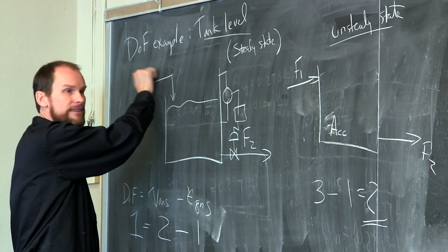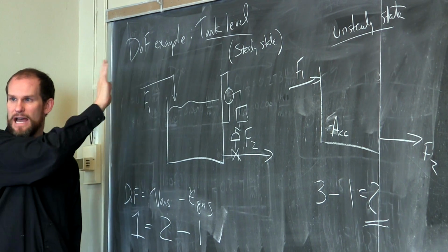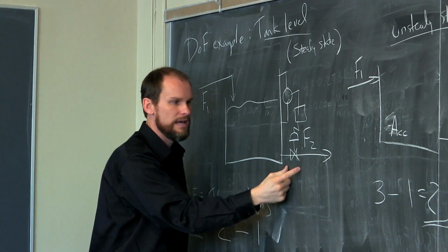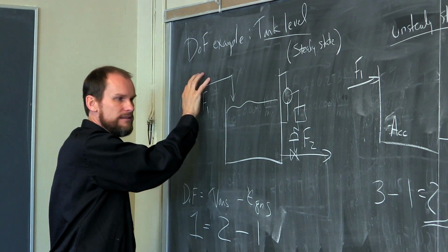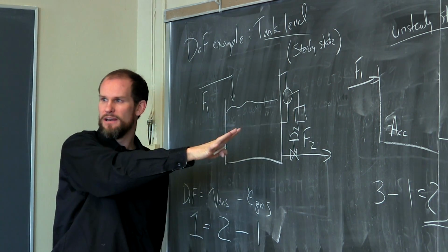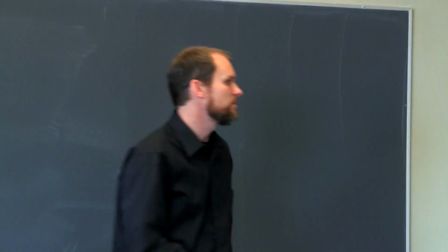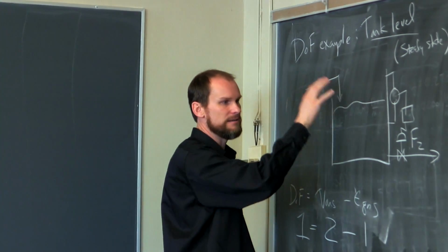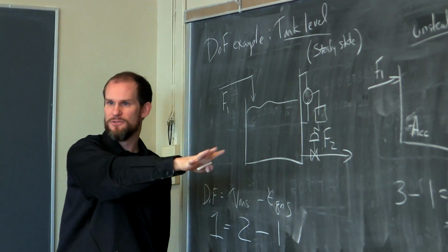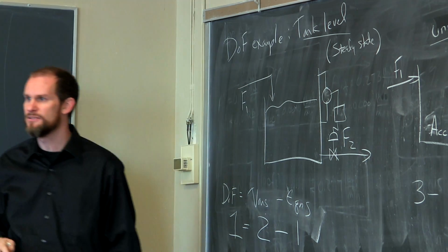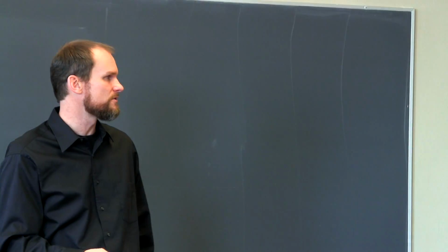And we might let this fluctuate because maybe it comes out of a reactor or a cell system or something that fluctuates and we can't really control. And we'll set this one, so given this, we'll set the flow rate and have that under control to keep the level steady. That might be a thing we would do. We could also put this control system on the front end and let this vary. Maybe it's downstream that varies, and then we want to accommodate for that. So we'll talk about that senior year in control class.